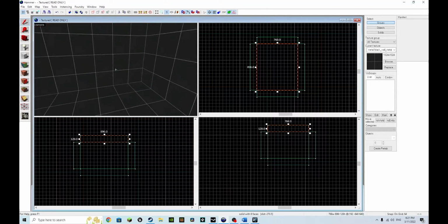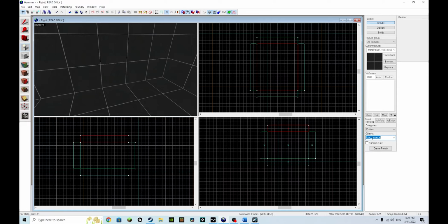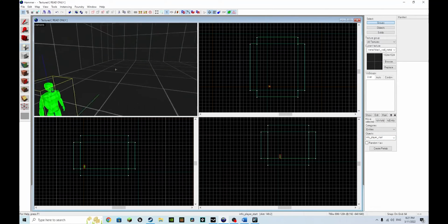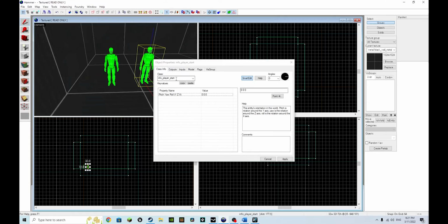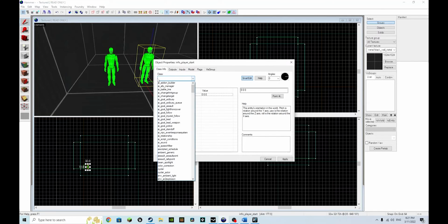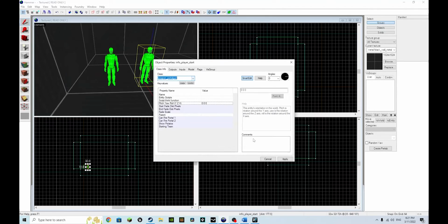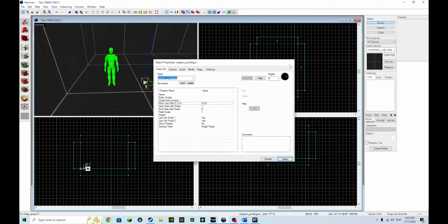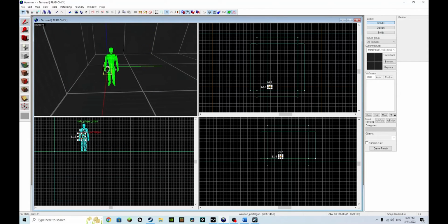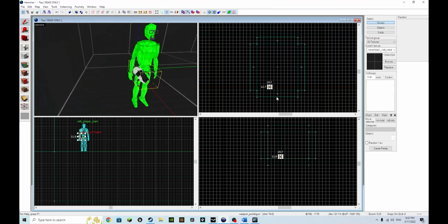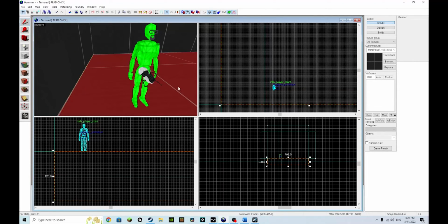We can also place an info player start, so our player has somewhere to begin their level. And if I go to selection and then double click, I can make this other one a weapon, portal gun. Make sure it has full functionality, and then if I expand my grid, I can move it over to my player. Ensure it is positioned correctly, and save this as first level.